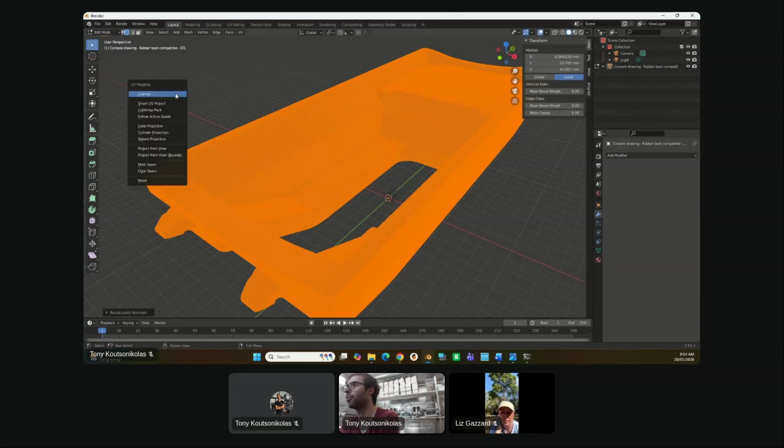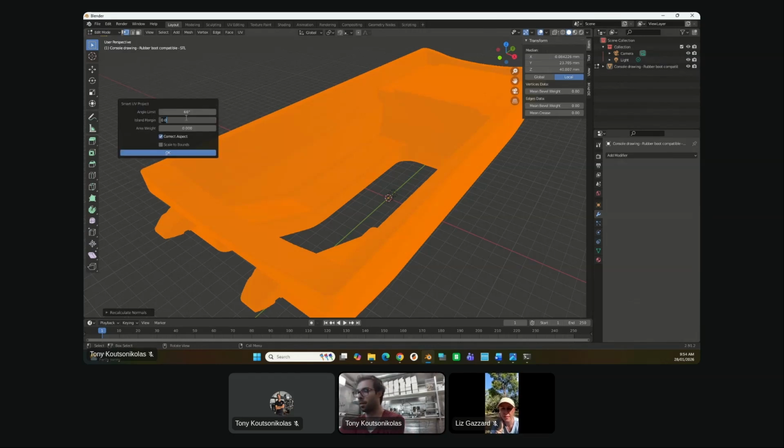We just press U, and then we go Smart UV Project. And then the island margin, we put this as a low value. This is another quirk. This is just the difference between when it reaches a boundary, how much it smooths to make it so there's no seam. So don't worry too much about that. Let's just go big picture for now, and I'll click OK.